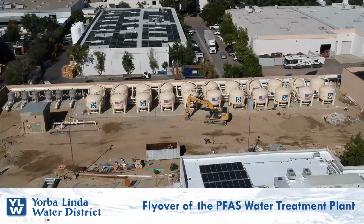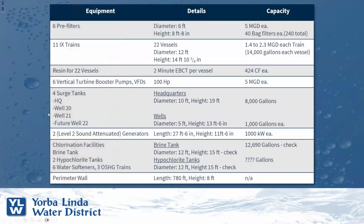And this is the site in Yorba Linda. It's actually at their headquarters. So the building here is their headquarters building. They are treating all the water in one location. There are 22 vessels, 22 12-foot diameter vessels with ion exchange resin, treating the water here in Yorba Linda. There are 6 pre-filters on this.